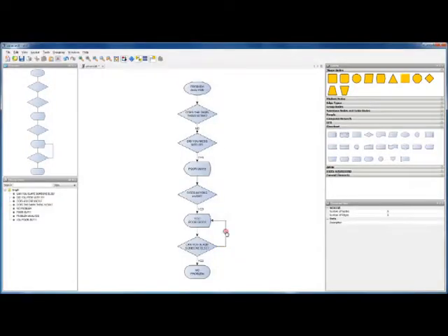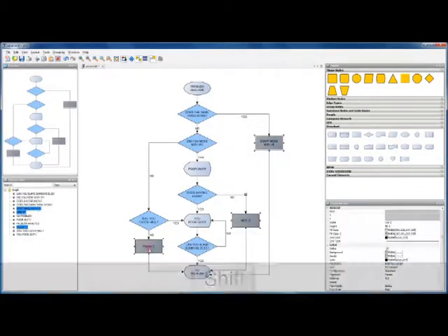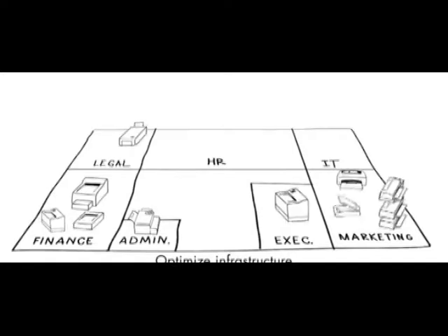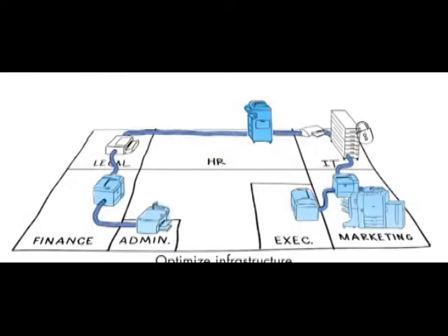Step 9. Study the material flows. Material travels according to the sequence of operations specified on the route. So you should analyze the material flow to find the most effective arrangement of machines, facilities, workstations, and departments. This is not only true for product flows, but for information flow as well. You can use this flow to place the service facilities conveniently for the employees and optimize the infrastructure by studying the material flow patterns to establish the shortest distance flow possible.